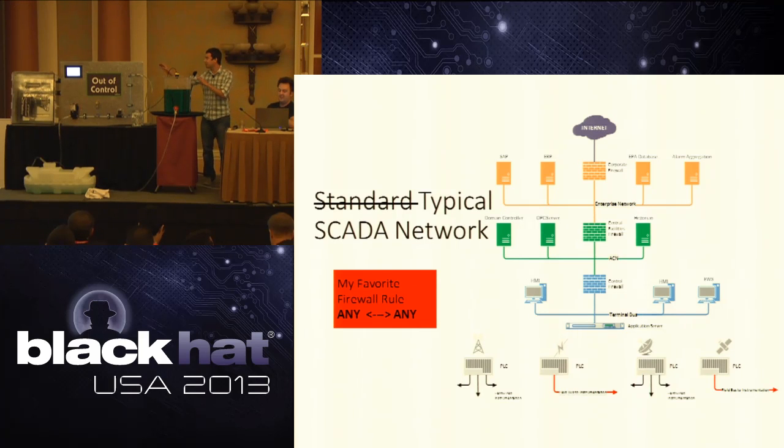That's right. So essentially what we see is routers, right, in this control system. For compliance's sake, they always have these firewalls in there, but all those firewalls are allow-any, and we see this in the field a lot. They design the segregation in there, but in reality, it's just a routed network, just like anything else.